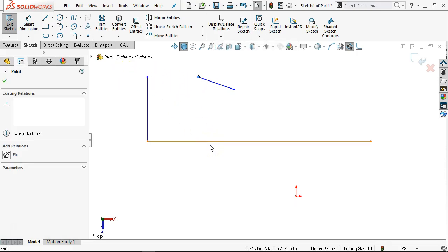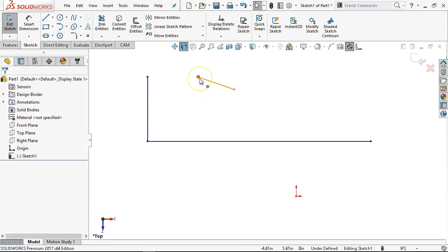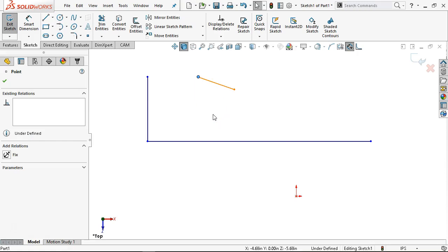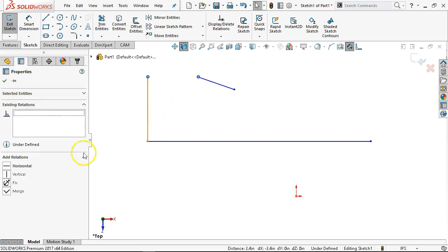So first time I'm introducing the Control Select. Let's run through that real quick. Primary function of your index finger is to hold down the Control button. So when I say Control Select, I select the first object, in this case the endpoint. I hold down the Control button, I select the next endpoint, and we have a merge.